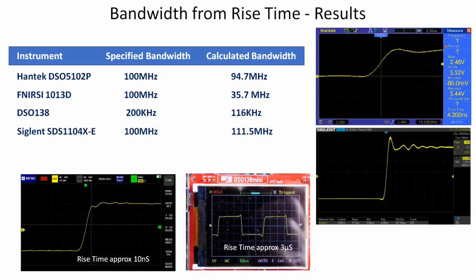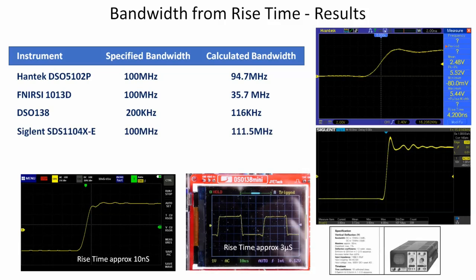Now finally, I've also got a 1970s analog scope. It's a Hameg HM307, and unfortunately I couldn't get a meaningful measurement because of the way the edge is displayed. I just couldn't get a sensible measurement at the fastest time base, which is 500 nanoseconds per division, but I couldn't even get the wave to display at that.